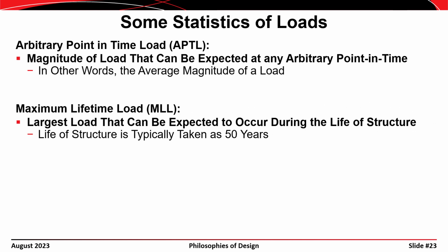The next term that we define is the maximum lifetime load. And this is the largest load that could be expected on a structure or in a member of a structure during the life of the structure. Now, as far as ASCE is concerned, buildings are designed for a 50-year service life. Now, certainly there are a lot of buildings out there that are older than 50 years. And if you look at bridges, AASHTO defines a service life as 75 years. But anyways, we define 50 years as our life. So a maximum lifetime load is the maximum load that can be expected over a 50-year period.